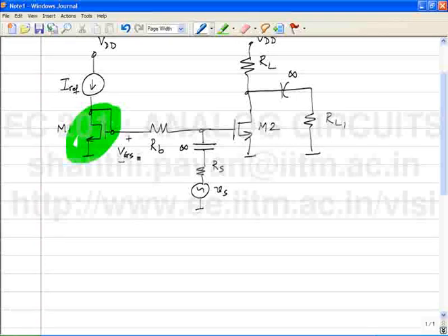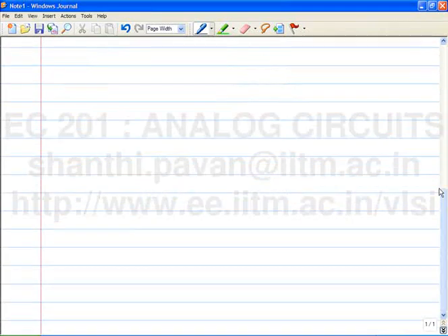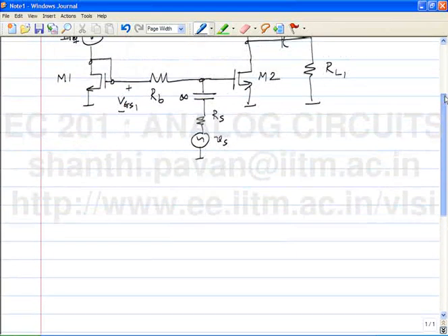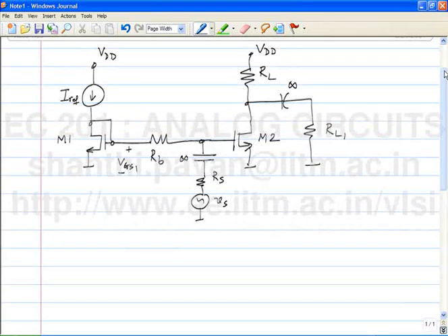Does that make sense? One could argue that this is a technique that's only appropriate for an integrated circuit, because when you're doing discrete circuits, if you buy two nominally identical FETs from a market, you will find that the thresholds are different, and so is mu and Cox and so on.